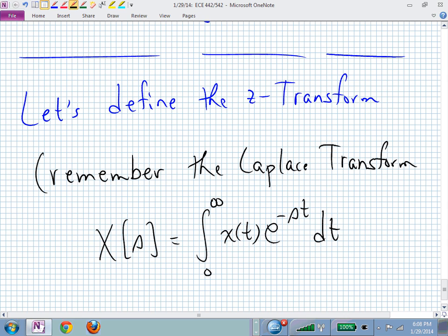So what are we doing? We are actually taking our time domain function or waveform, little x of t, over all this time horizon. We're weighting it by this kernel or this complex exponential and integrating that over all time to boil down the frequency content in that signal, or the S domain or the Laplace information in that signal.